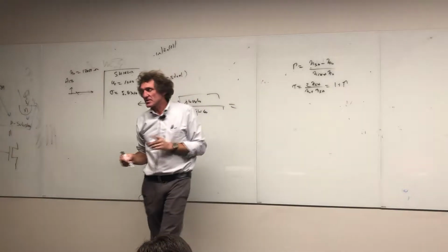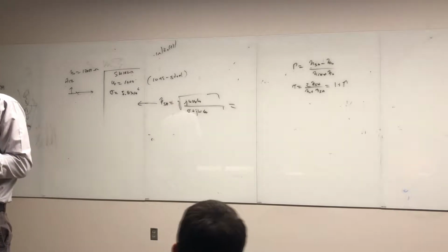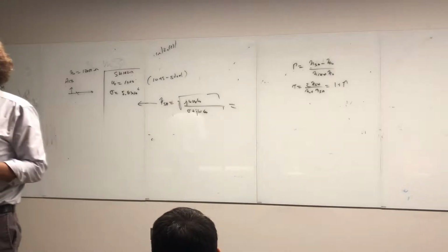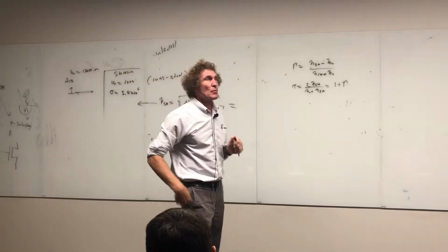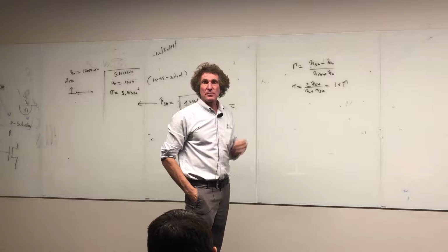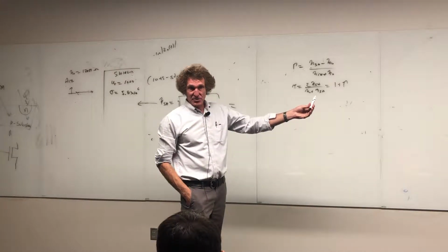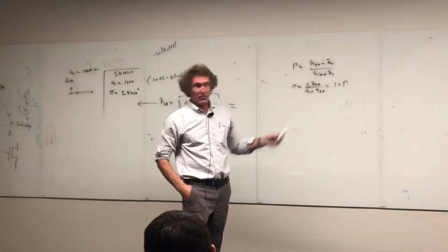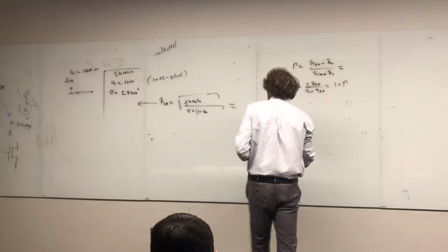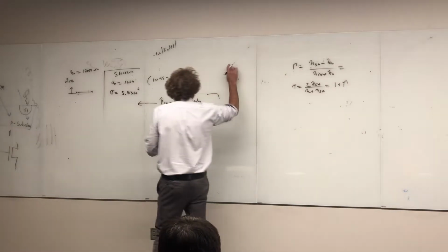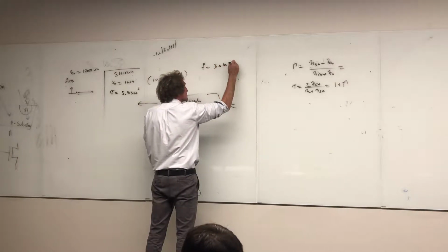Now, the thing is that reflection coefficient is going to be darn near 1 or minus 1. And the problem is if you do rounding errors, if your calculators aren't set to do 6 or 7 orders of precision, in other words, you can't round that just up by 1 or else you're going to get a wrong answer. For this one, when you do it, what do you get? Well, first, what are the frequencies you want it for? Just tell me. 30 megahertz, 100 megahertz, and 1 gigahertz.